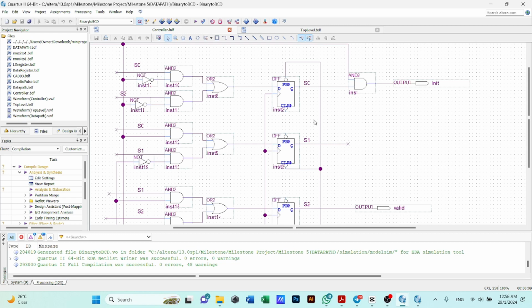Whereas when either S0 or S1 as well as go is set as high, which means the sequence coming from go, so initialization will be verified, then the state will jump from S0 to S1. In S1 we're going to perform the binary to BCD conversion.